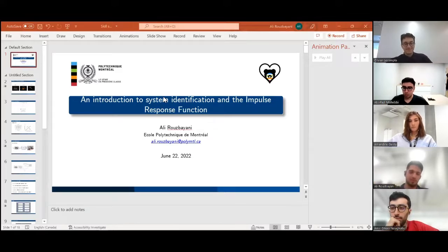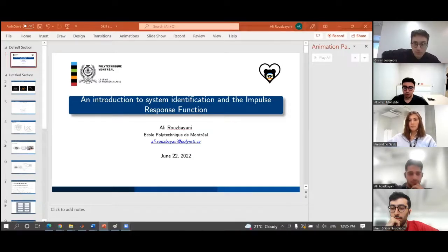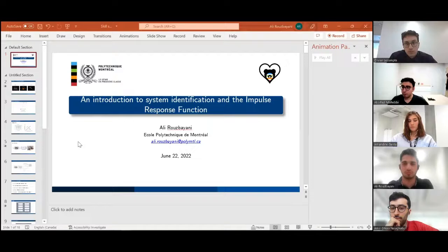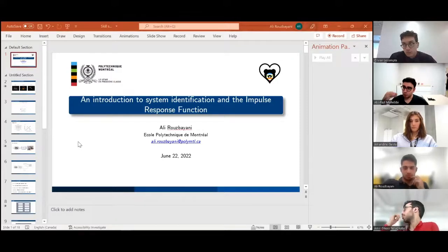That was a good answer. So what Ali was trying to say was that when we're using parametric system identification, we have a model structure, a model that represents the physics, the dynamics of the system. And then from this model, using the system identification approaches, we're going to identify the characteristics, the parameters, the values. But with all the black box approaches of deep learning and machine learning, it's a completely different story.